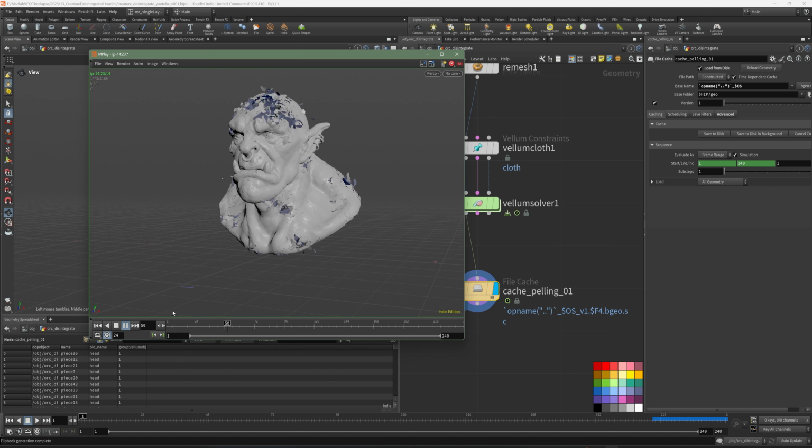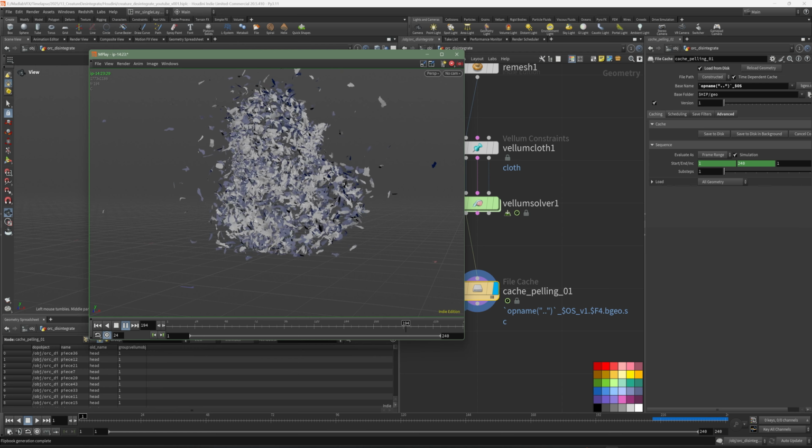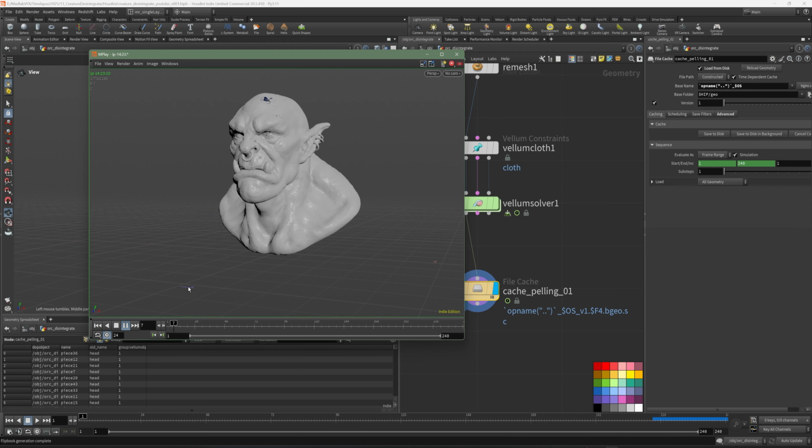This is the first simulation of these fragments. The fragments are just floating and are not activating like the mask. We need to create a mask to activate each fragment to start simulation at its respective time. To do that, we need to create a mask. And before creating a mask, this cache took around 4 minutes to take. We don't need to cache the whole geometry again.